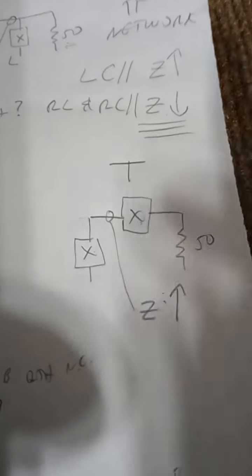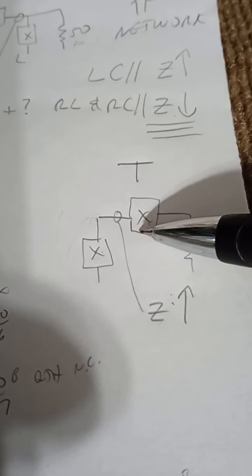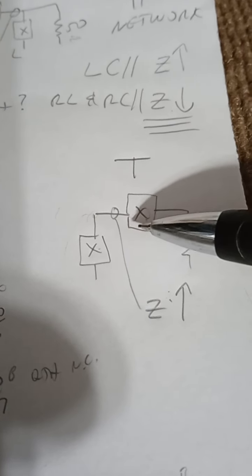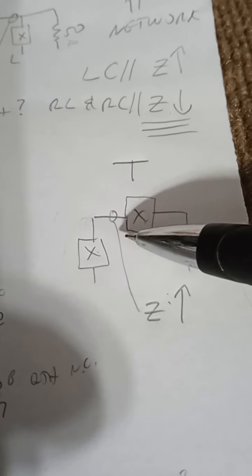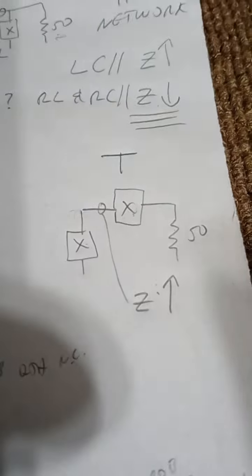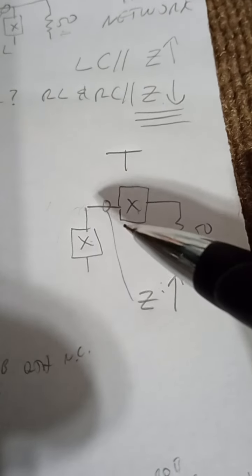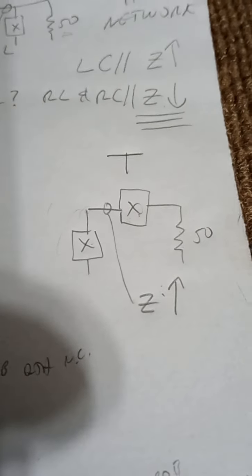These two aren't so critical because it's low impedance. But if this is tending to go towards resonance, which is where the step up in resistance is, then if these reactances are chosen too close together, this circuit will be very critical. So it's necessary to do what ifs, several calculations, and make some difference in these two reactances so that circuit isn't quite so touchy.